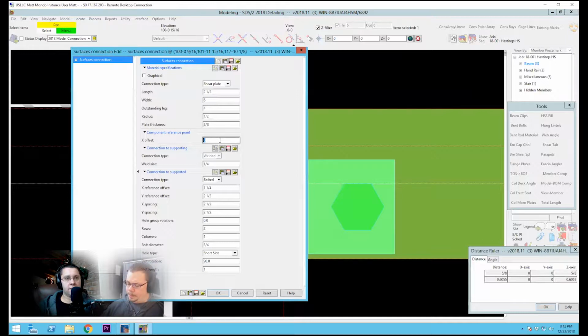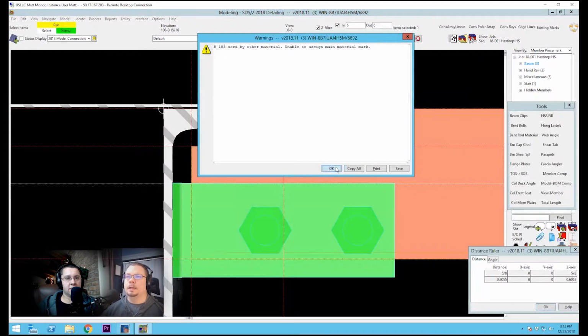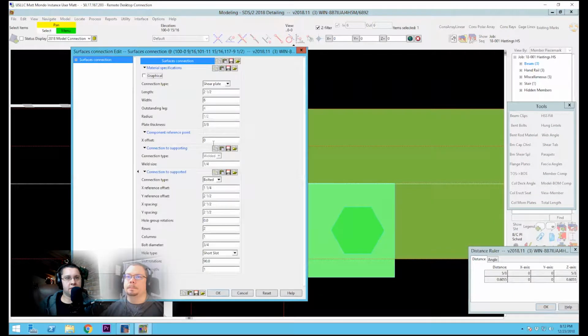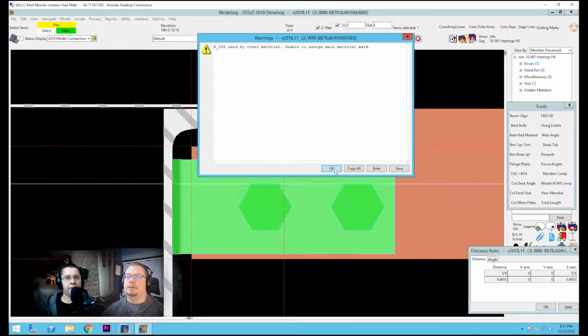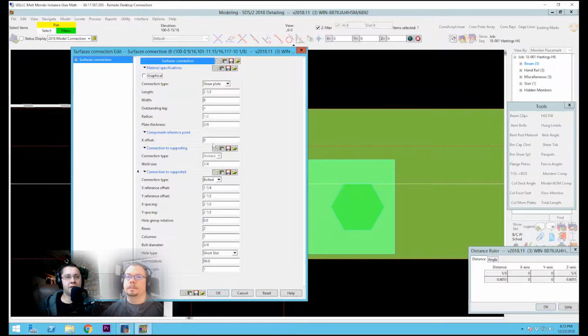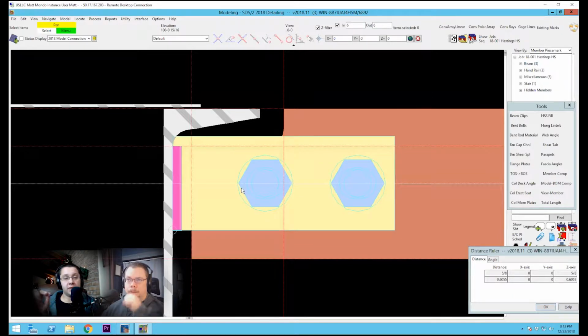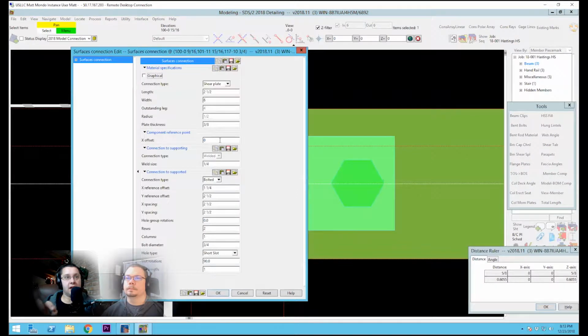So if you screw up, and let's say you went the wrong way in the first place, and I went minus 5/8 and I dropped it down even lower, I now need to compensate double that amount in coming back up. Yeah. So if I go 5/8 back up, it's just going to push it up that amount that time. Yeah. The title of that field should really be adjustment, right? Like it's going to adjust it this time. So make sure if you do use the save dialog tool, do not save that adjustment field in your save dialog, or you're going to have a bad time. Right. Leave that zeroed out when you go to save this as a form for putting these in en masse later on.